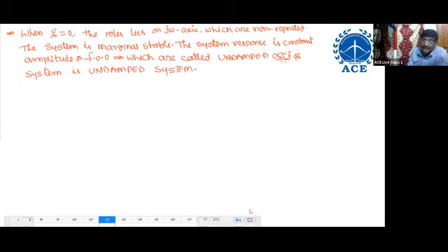Right. Next. Can you find the steady state errors when zeta equal to 0? Anybody? We cannot find them because the system is marginal stable. Steady state errors are valid for only closed loop stable systems. When zeta equal to 0, we cannot find steady state errors.